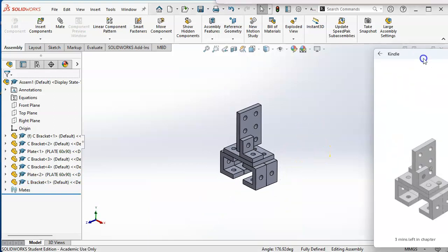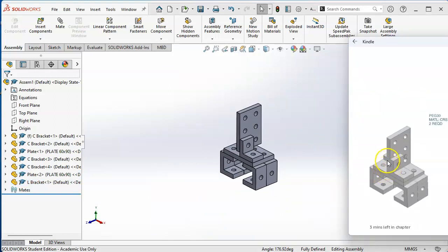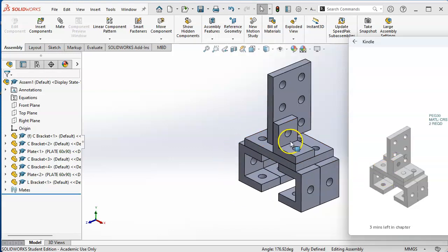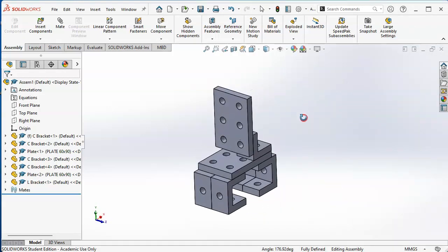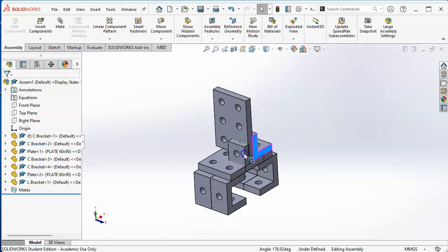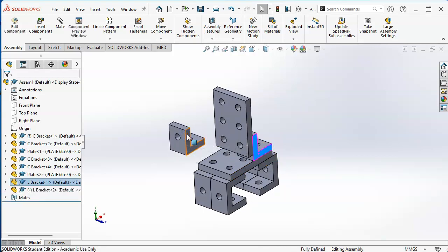All right, so if I drag the picture back in, notice that this is touching. That means that they went coincident, and the error check is that neither one of those holes are going to line up to the pegs. All right, so a select, control select, or I'm sorry, a select, control drag, let go of the mouse button, let go of the control button.